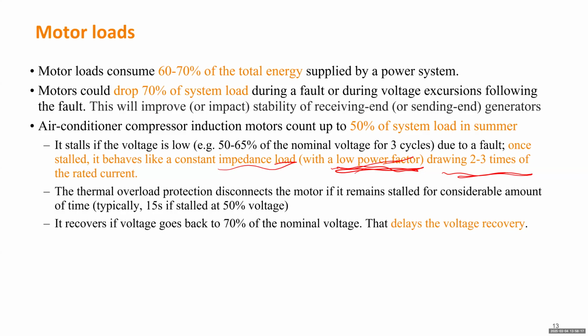Then after the fault is cleared, when the voltage recovers, the induction motor will think, okay, so I need to go back. So they will restart. But restarting an induction motor also needs a lot of reactive power. Okay, the worst case will be some induction motors will keep stalling, restarting, restarting. So for a long time, that will consume a lot of reactive power after the fault. That time can last maybe 30 seconds.